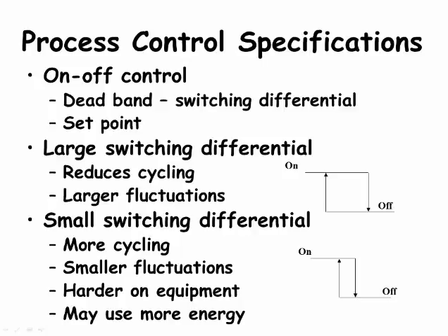The operation with the standard on-off control had each pump turned on and off roughly 170 times each in a 24-hour period. The operation that had the 2 variable frequency drive well pump motors only turned on and off a total of 38 times over a 24-hour period. The one pump turned on and off only 8 times in the 24-hour period. The report indicated that the operation with on-off control could save over $2,300 per year by installing variable frequency drive controls on the well pumps.